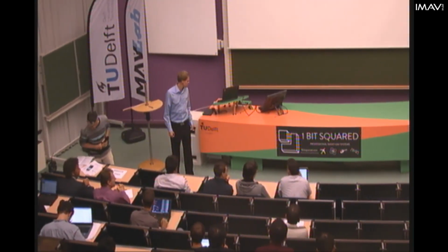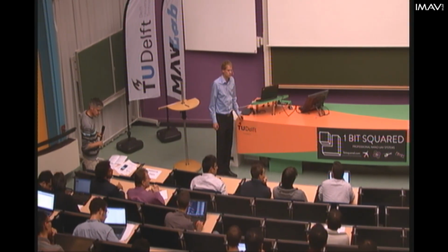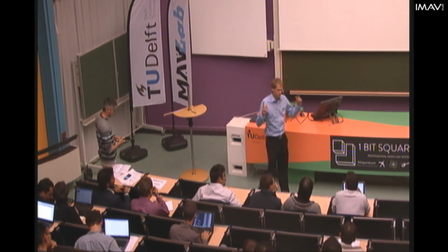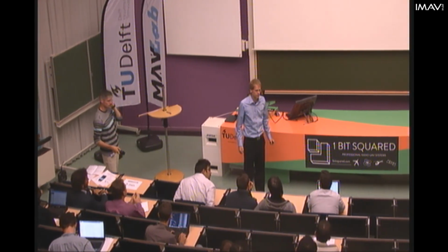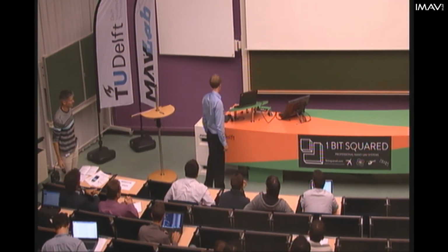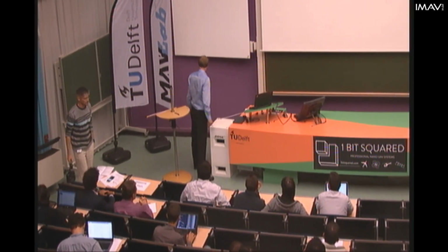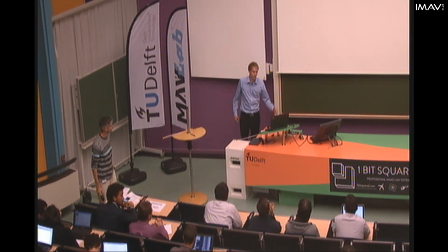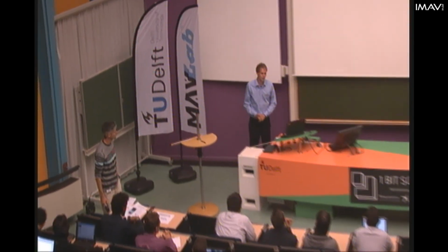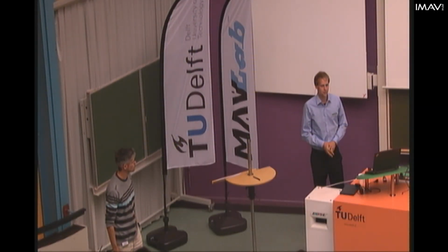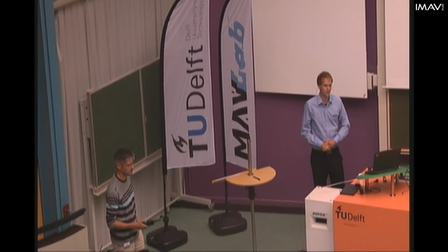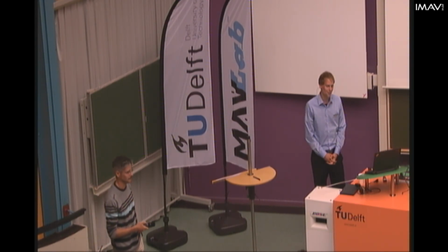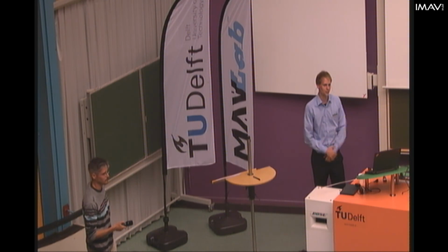Have you thought about using variable pitch propellers and see how that would improve things? What kind of variable pitch? On the main propellers? Yes. No, we did actually not do that because we already have huge problems with variable pitch on a propeller on our tail. So we are already trying to get rid of that, and we don't want to have more mechanical problems on the main propellers. But yeah, that might be interesting for pitch control, of course.